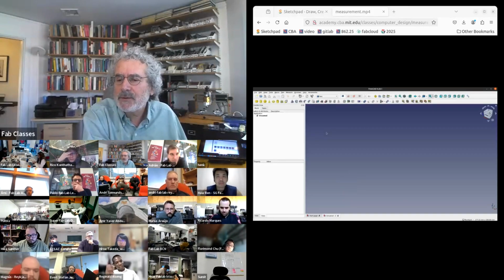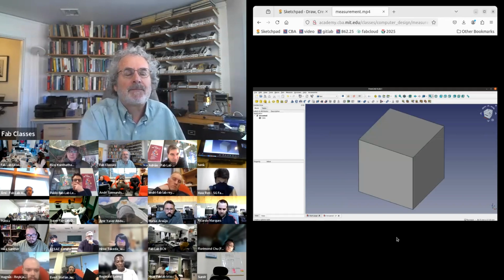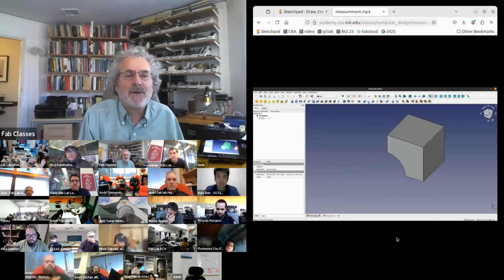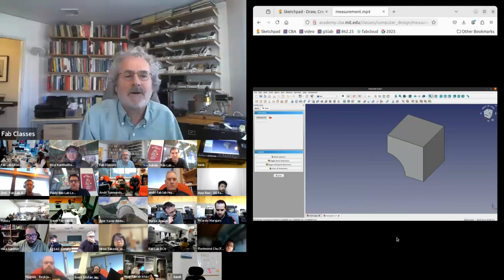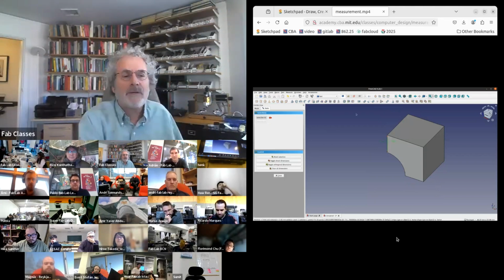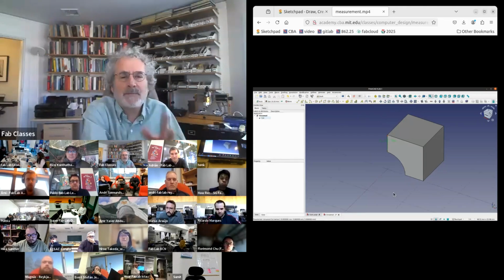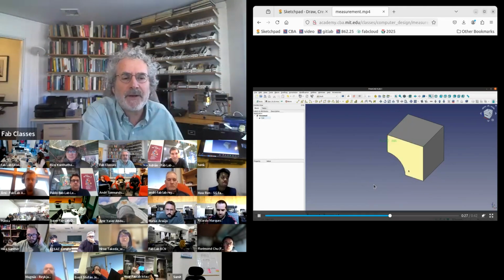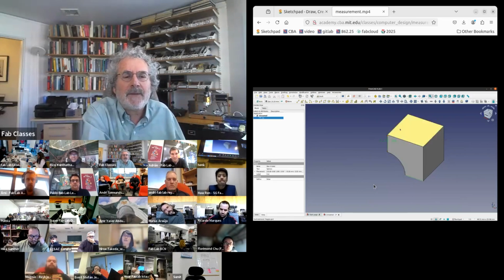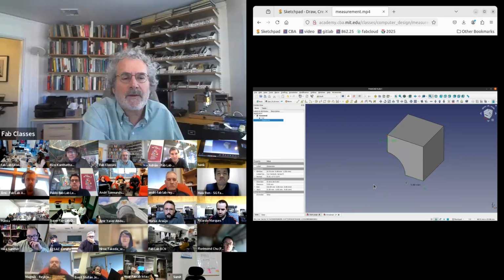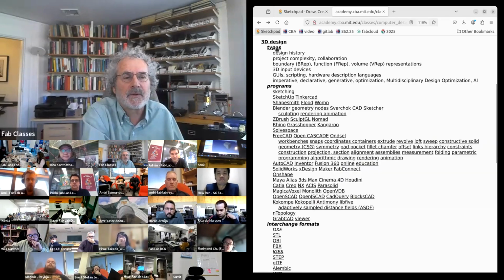Because of all these solving tools, you can make things and not even know the size and shape. So an important thing you can do is make measurements on your design. Here I'm picking some points, and then it'll give me a readout of the coordinates. If you don't specify the dimensions after a set of operations, the measurement tools are handy for that. And here I'm adding a dimension to the drawing.